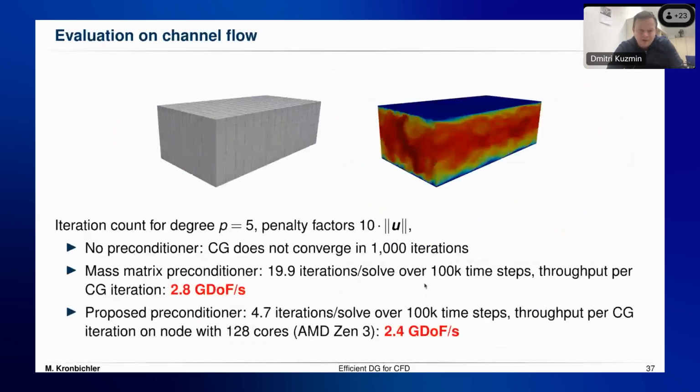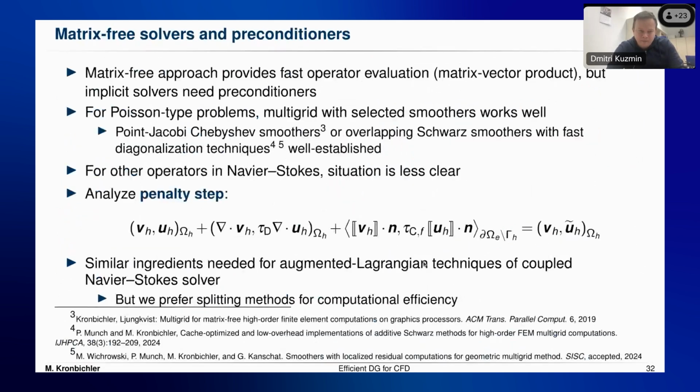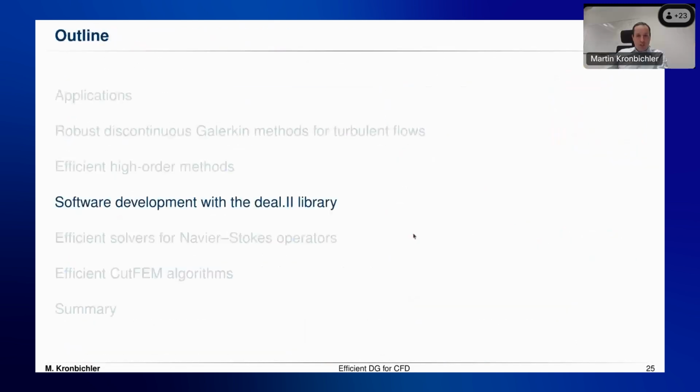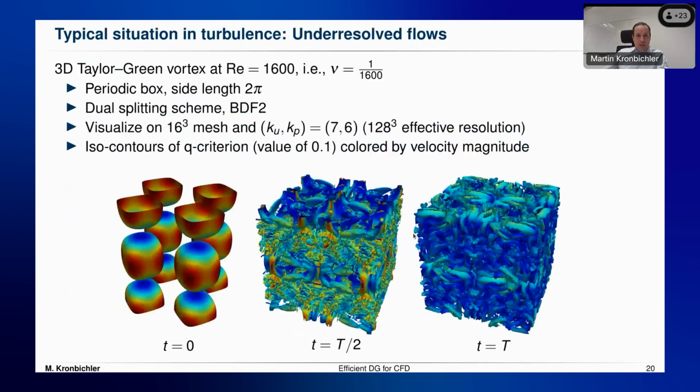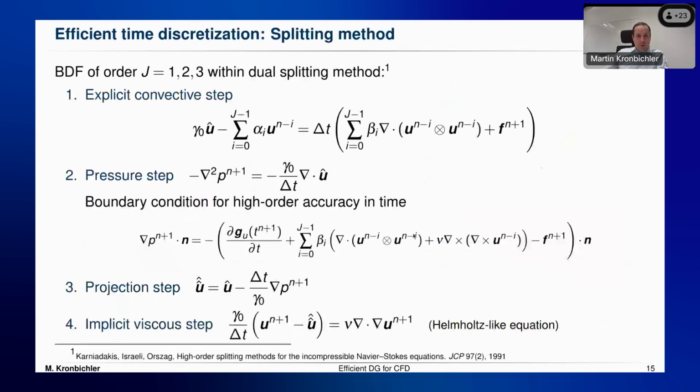That's a good question. I should mention that the particular projection type that we use belongs to the incremental type of projection methods. So this is actually a high order one because of the extrapolation from the old time values. Essentially, this can be as accurate as the BDF method. So you can do BDF2, so you can do second and third order accurate methods. So there is some incremental version of this one.